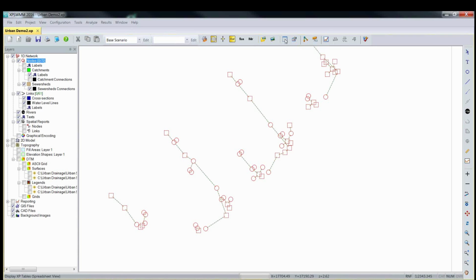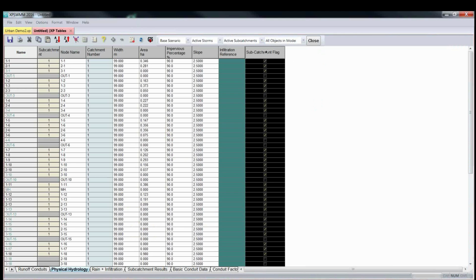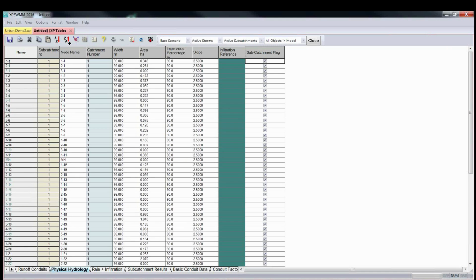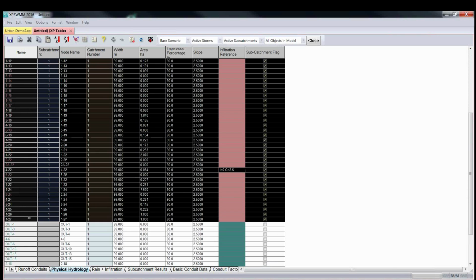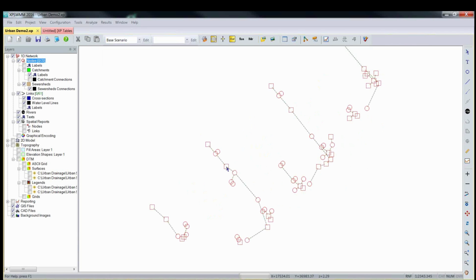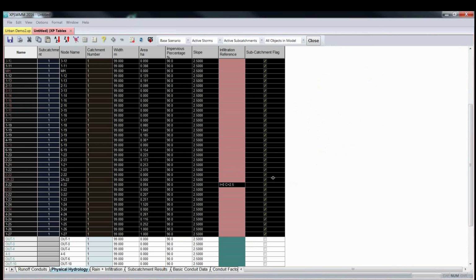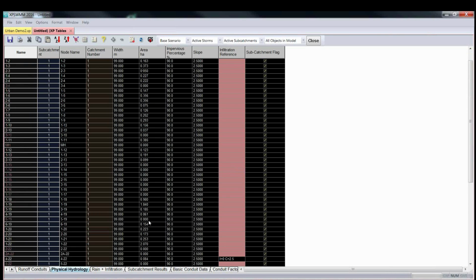Hopefully, probably only the second last time I'll need to go into XP tables, but what I'm going to do now is, now that I've disabled all of those components, I'm going to sort, again, Z to A, and this time I'm going to highlight the nodes that actually are selected catchments. From this point, oops, it's actually picked up one there that shouldn't be a catchment. I must have turned one off. I want to do that again. I did too. I must have missed 2 lines up, but that's okay. I'll play on for today's purposes.